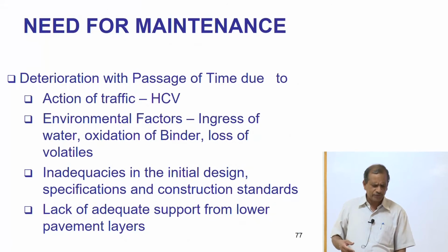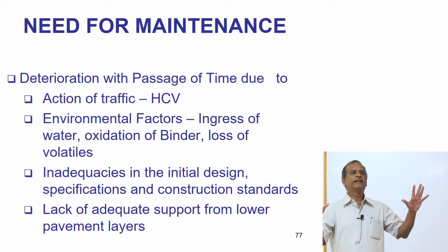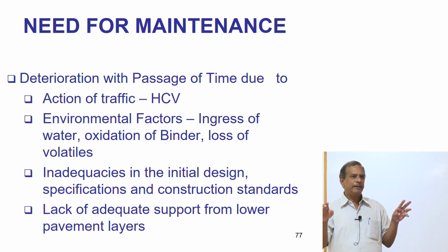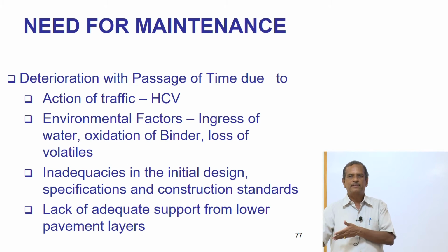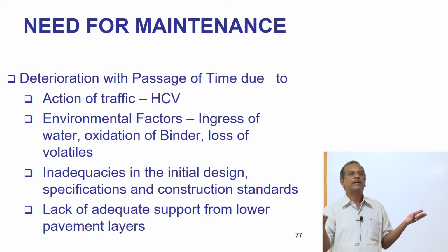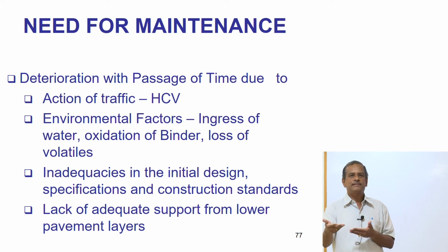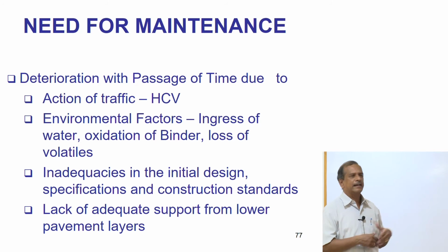The other issue that you have to face is that all the roads will deteriorate. When there are different types of vehicles on the highway, cars, two-wheelers, auto rickshaws, trucks, buses, the majority of the distress on a pavement is only from the commercial vehicles. So more the commercial vehicles, faster the deterioration if you have not accounted for it in the design. So one factor is the heavy commercial vehicle which causes the deterioration of the pavement.